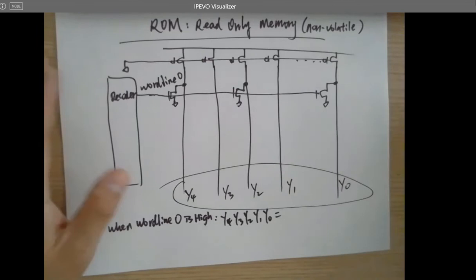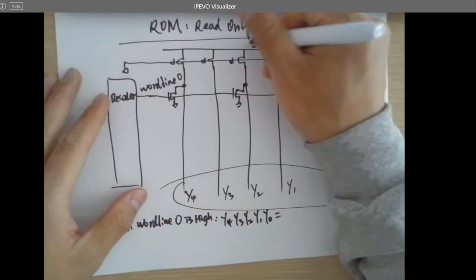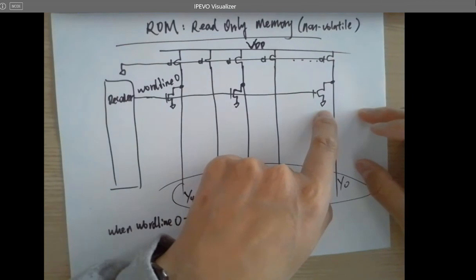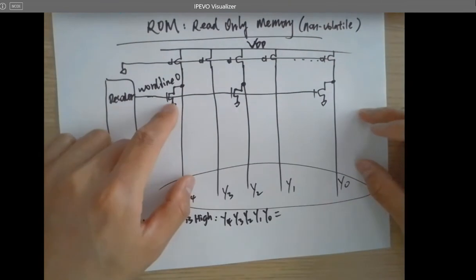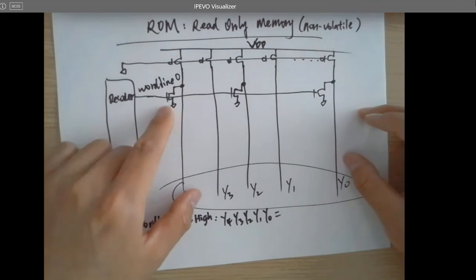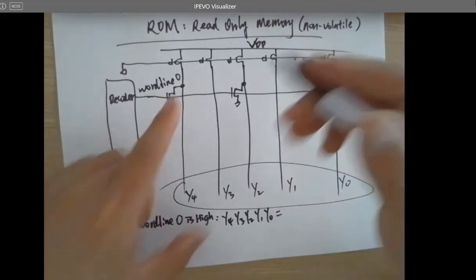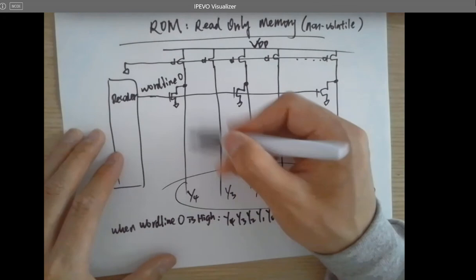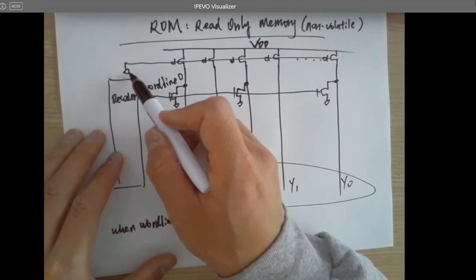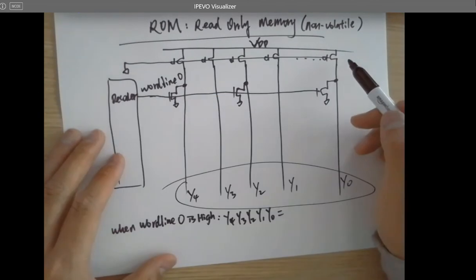It's still competing, right? We just want to make the NMOS stronger. Because if you do not make the NMOS stronger, it's not making sense to have an NMOS here. Since whenever we have an NMOS here, we just want to pull this data line to 0. Because at the very beginning, all these PMOSes are being turned on. It's a ground. So they're always on.